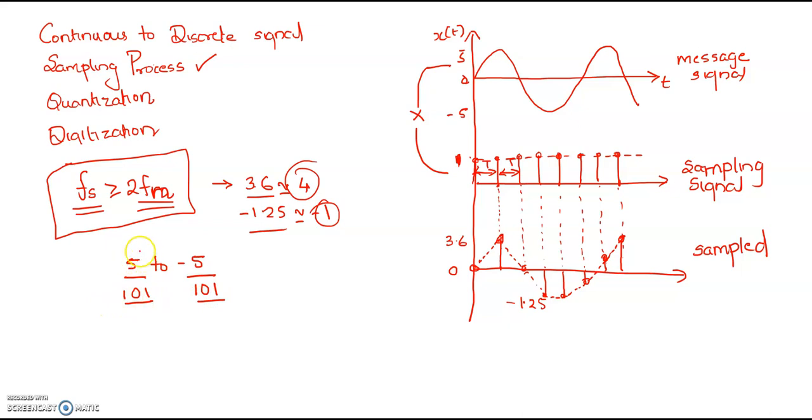But then how do you differentiate between these two? You need a sign bit. So let us assume 0 is used here and 1 is used here. So 0101 will represent 5 and 1101 will represent minus 5. So with this the digitized concepts can be implemented. So a value like 4 will be stored as 0100, and a negative 1 will be stored as 1001.